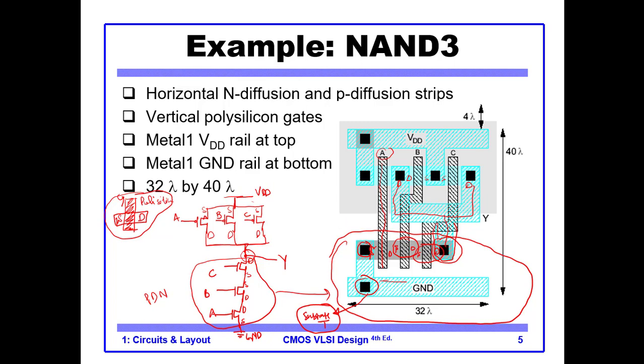Okay, so let's see, this one is again transistor A, and it is connected to the VDD. This is again the N well tap, so this is the fourth terminal, and then the VCC is connected here. So you see the source of B and the source of C, they are both here. Okay, so this is important to understand. They are both connected to this point, and they are both on this side. So this is how a NAND gate is formed.